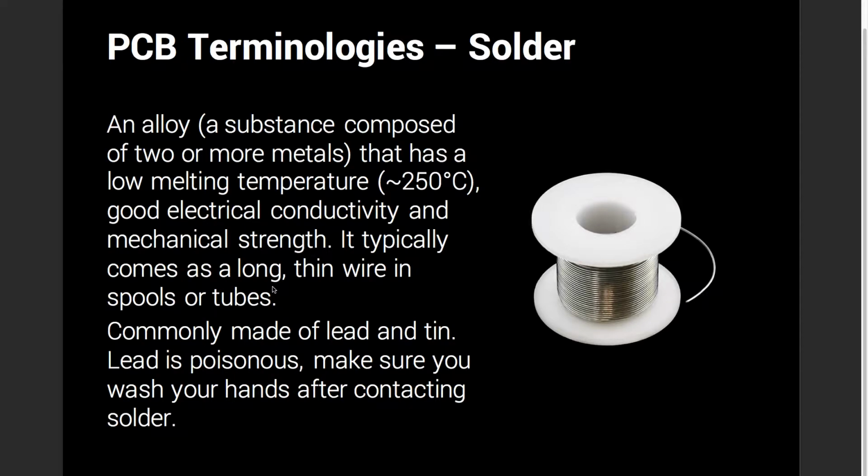Solder. It's an alloy composed of two or more metals that has a really low melting point. Before, it was lead and one other metal, very leaded, and I think some of our solder is still leaded. So after you solder something, it's very good to wash your hands, because you don't want to get lead poisoning, because that's really bad for you. So remember that. Solder provides good electrical conductivity and mechanical strength. It typically comes as a long wire, a spool of wire, or tubes.